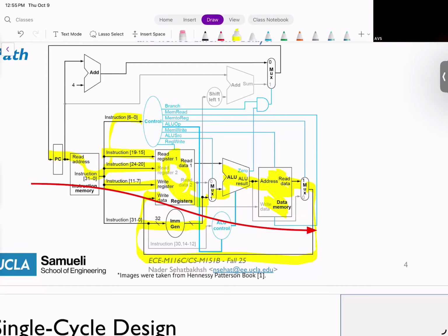And this, unfortunately, is very, very slow. Even though we simplified the memory, telling you that memory is just within one clock cycle away so you can read it instantly, in reality reading from memory could take hundreds and hundreds of cycles. The bad thing is that you cannot have a dynamic clock cycle. It's not like if this is an add, I clock faster, and if it's a load, I clock slower.